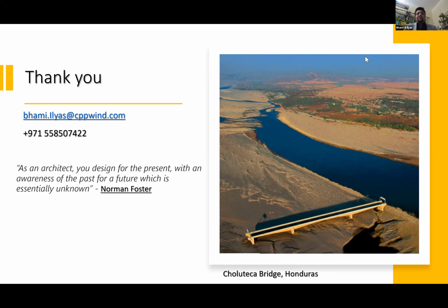It's a very fundamental and interesting question, because we could go on and on in terms of the factors determining the pressure acting on the structure. It would start with the structure, of course, how the architecture of the structure is. Then we have to look at what city this structure is located in, the climate part of it. We have to look at the proximity, what kind of proximity this particular structure is located in. So these three would be key.